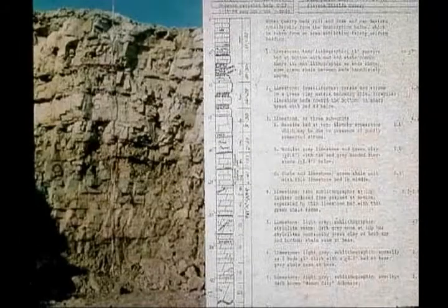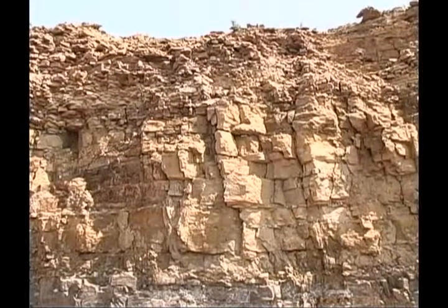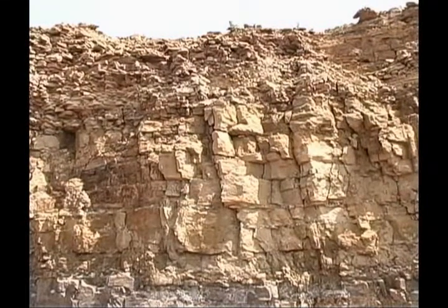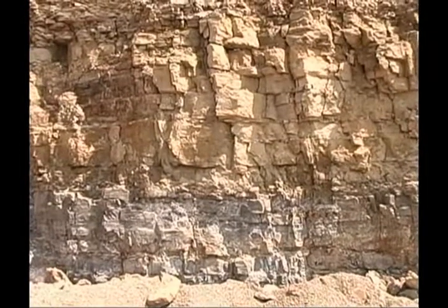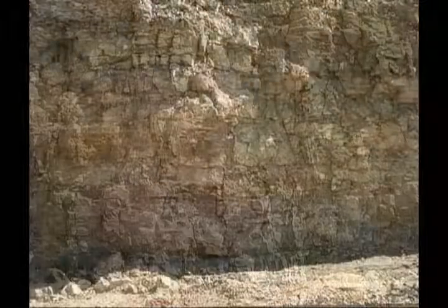Quarry logs are on file at the Materials Office, which give a brief description of the type and thickness of material present at most quarry locations. Once the appropriate bed numbers are determined, the beds should be identified in the quarry face. Marker beds are sometimes used to identify the different beds in the quarry wall. These marker beds are usually chert seams or shale seams that run throughout the wall.